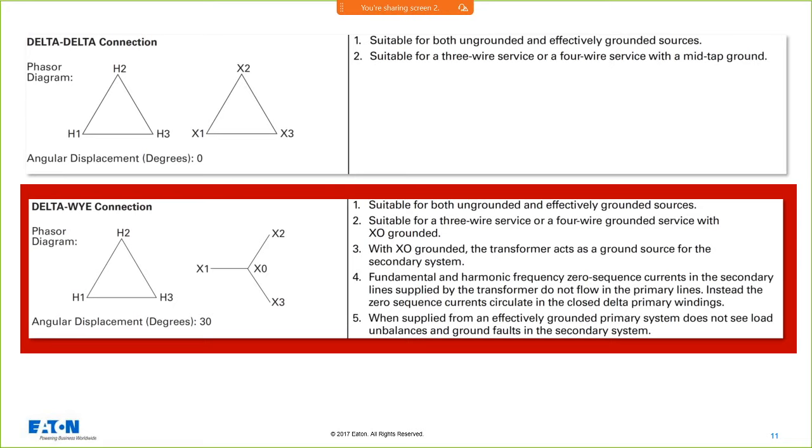They said, hey, I'm going to establish a ground, and they started that by corner grounding it. They created the zigzag transformers to ground power distribution systems because they wanted that anchor for that boat, so they didn't have to worry about all those surge voltages. But again, they sidestepped one problem, which was the overvoltages, but then they created the other problem, which was high fault currents when they grounded that system. But we learned to deal with that.